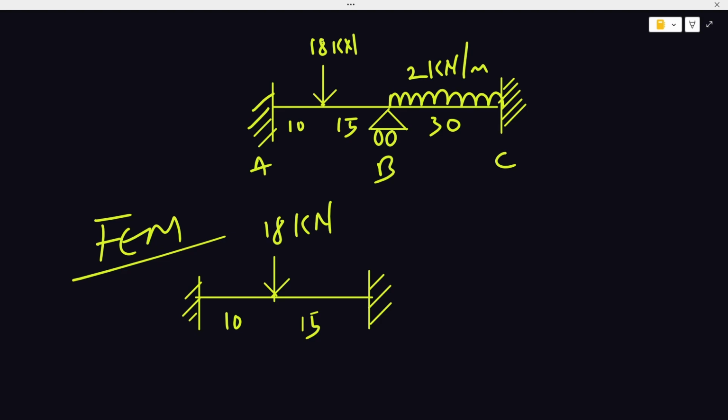Now, in my derivation for M equals 2EI over L times 2 theta, I assumed that anticlockwise is positive. You can check out the slope deflection derivation video earlier. So I use this sign convention where counterclockwise is positive and clockwise is negative.